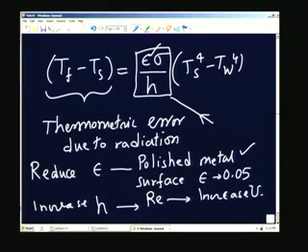and in fact, the advantage of such an arrangement is that radiation shielding also comes into the picture, because the converging diverging nozzle can be made out of highly polished metal, so that the emissivity is small, and at the same time it accelerates the fluid to a higher velocity, and therefore the Reynolds number increases, and when the Reynolds number increases, the heat transfer coefficient increases.